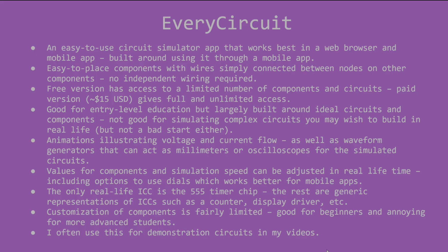It also has waveform generators that can act as multimeters or oscilloscopes for your simulated circuits. The values can be adjusted in real time and they can either be typed in or there's even dials that allow you to simply use your finger on a touch screen, which can make it a lot easier there. There's only one simulated real life integrated circuit chip, and that's the 555 timer chip. There are some generic ICs such as counters and display drivers and whatnot, which, if you understand those, you can transfer that knowledge to actual real life ones.